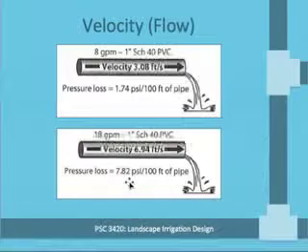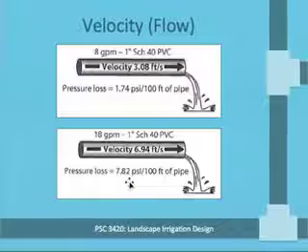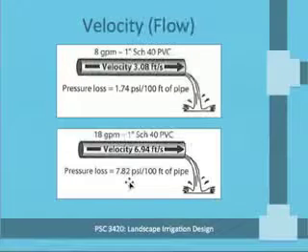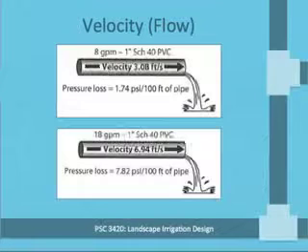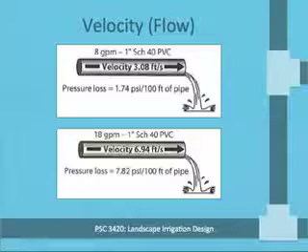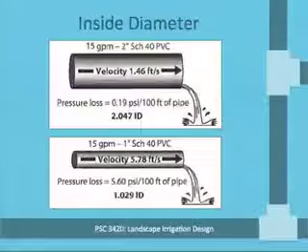And by the way, when we talk about friction loss, we typically use units of psi per 100 feet of pipe, but for lengths of pipe that are more or less than 100 feet, the friction loss is simply increased or decreased proportionally. And we're going to go through how you determine that in some later examples.